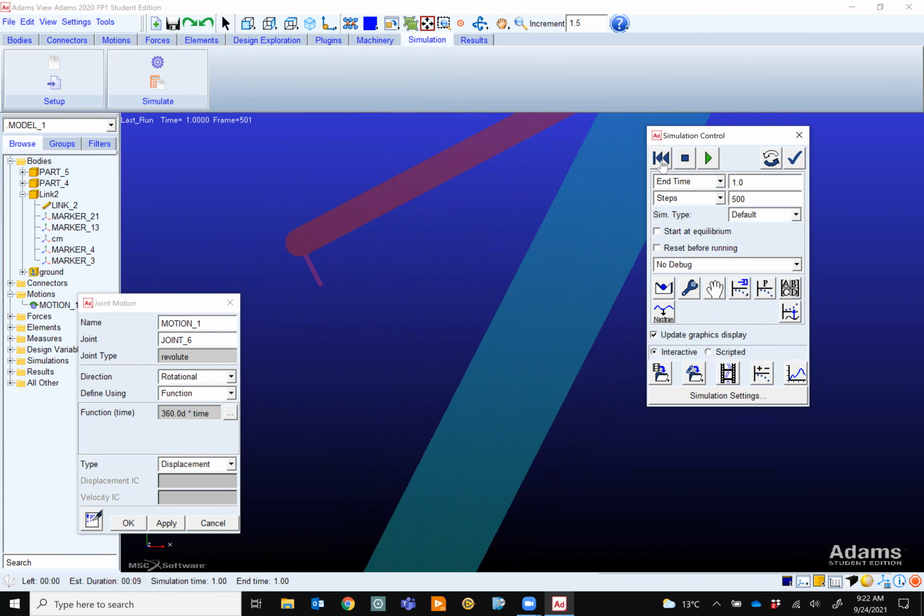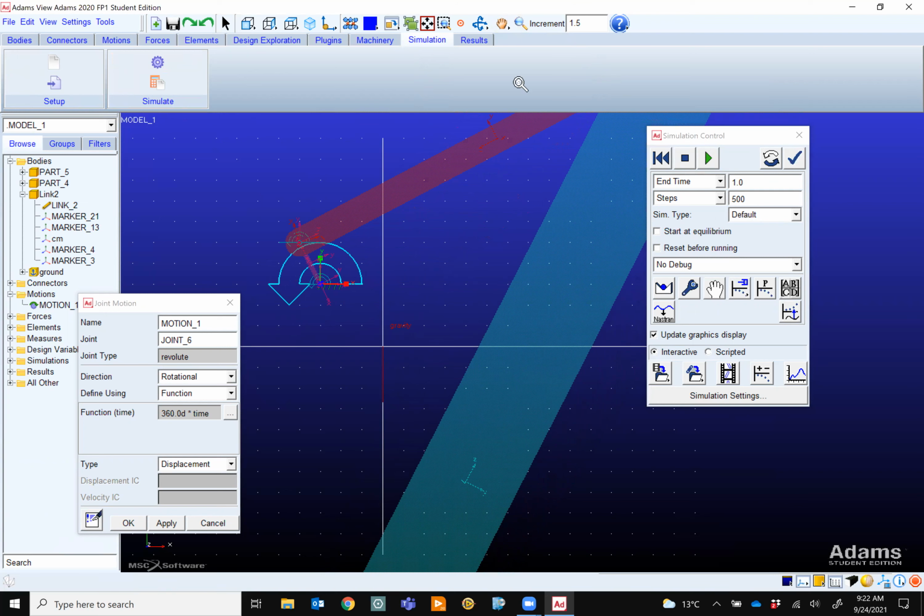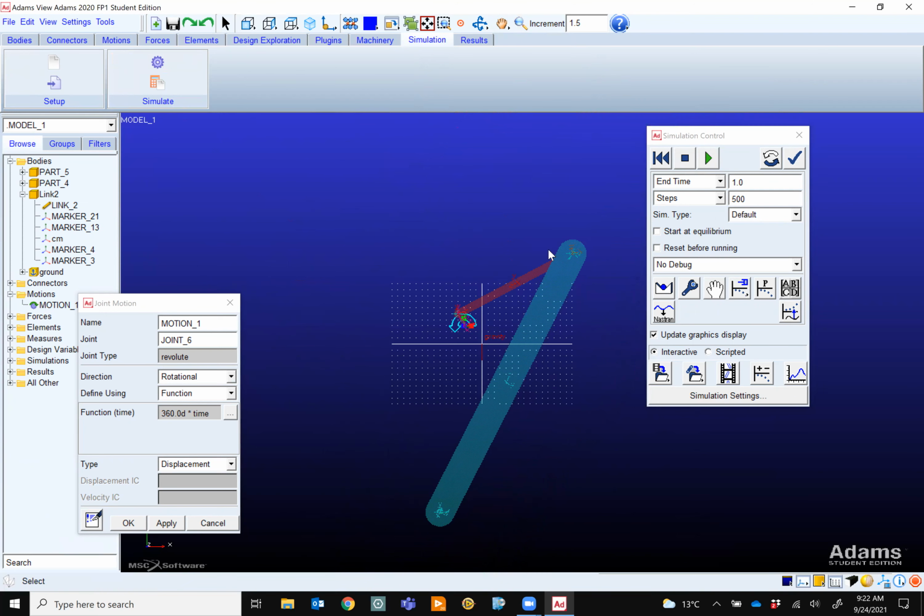Hey, success. Okay, so this mechanism now works. You see, the problem wasn't Atoms. The problem was that we have to have the right size. If you build your sphere robot in Atoms and those intersections don't intersect at one point, the mechanism starts working up to some point and then stops and gives you an error. It says that in practice it's not possible. The same here. If you build this mechanism, it's possible to run it. That's why the geometry works fine.